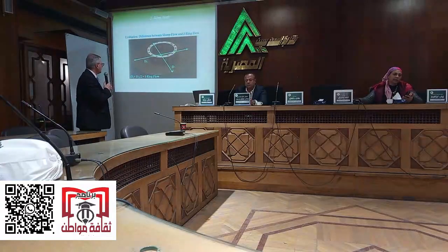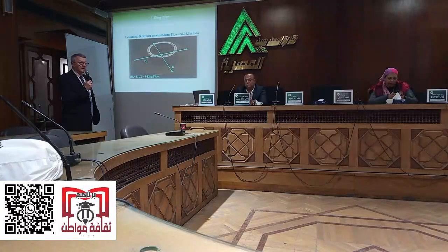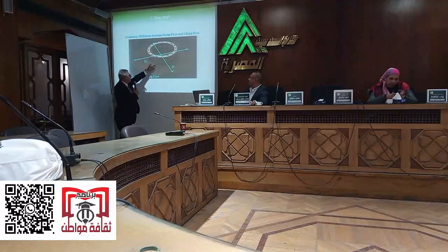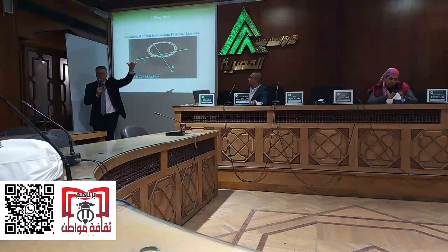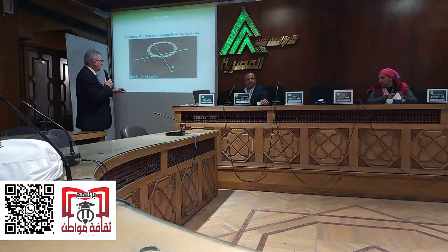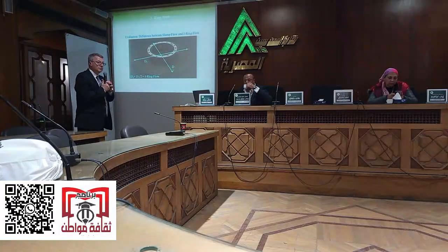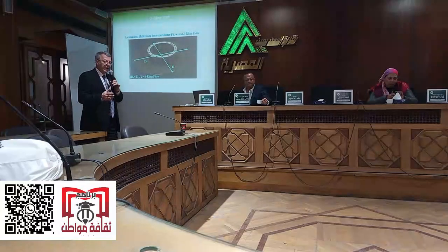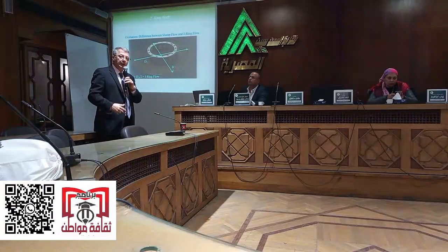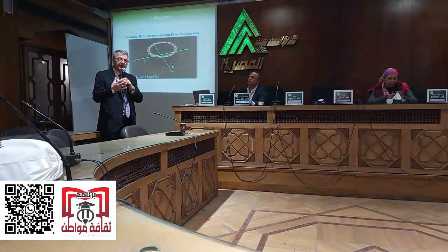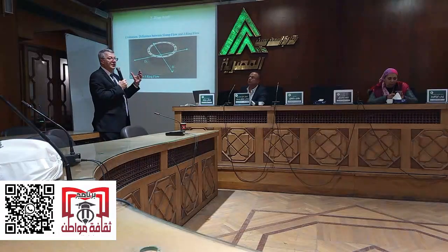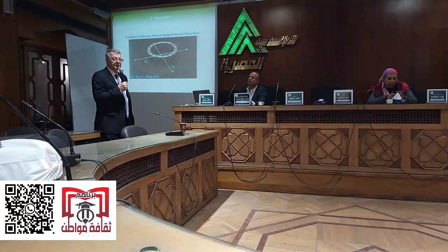So the J-ring is the same test as the slump flow, but you put a ring that has 16 rebars, and there's an opening here about 38 millimeters. So if you have an aggregate of 25, it's 1.5 times, and you measure the diameter at the ends. So if the diameter is low, that means the presence of rebars is really restricting the flow. And we call that passing ability. The passing ability is low. If the slump flow is very high and the J-ring is very high, that means the passing ability is also high.